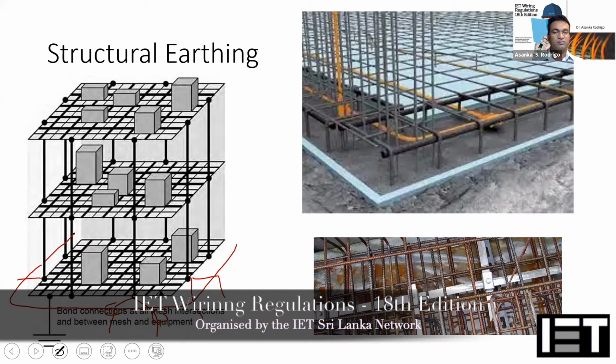Next question is regarding the RCD sensitivity. When multiple levels of distribution boards are present, should 30 milliamperes be at the final distribution board? Question is clear? Well, I think he's asking whether 30 mA should be at the final distribution board. Yes, 30 milliampere is mandatory for the final distribution board, where you cannot have more than that, especially for highly sensitive equipment and induced equipment.